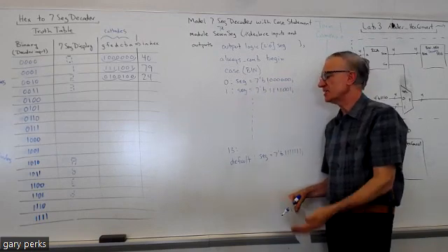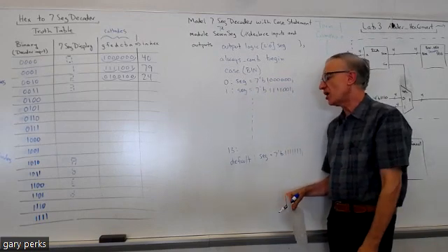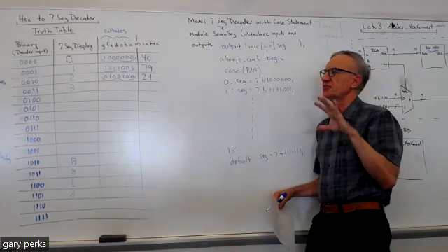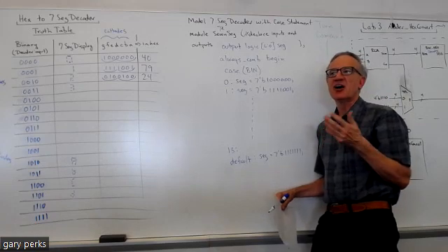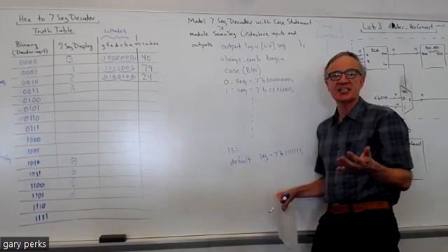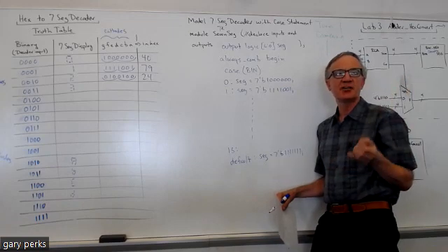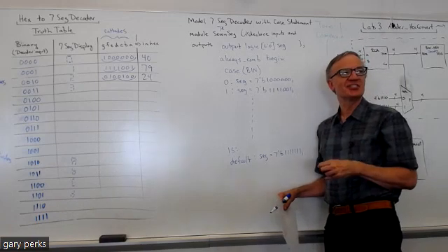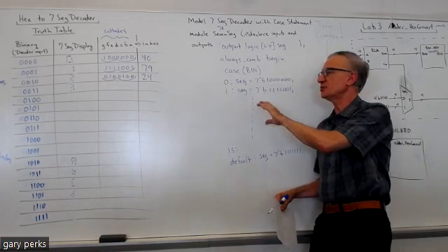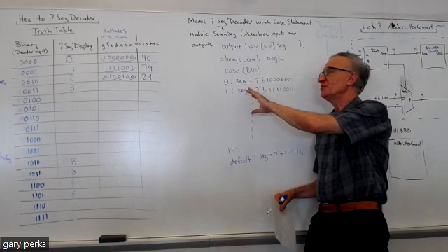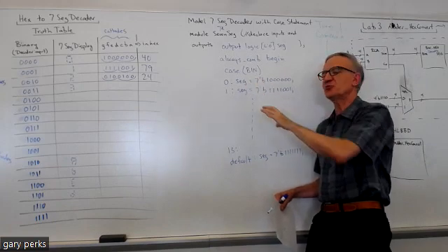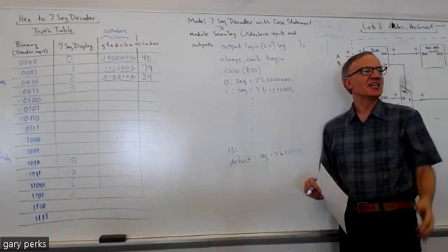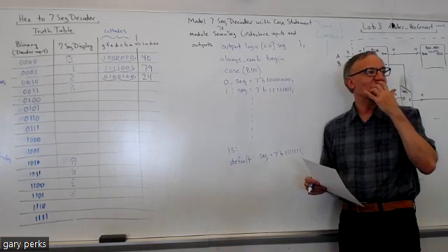I mean, an example in practice of why you would want a default is if you had some digital system that was in a harsh environment, like maybe it was on a satellite and the satellite got bombarded with solar flares or something. There's a bunch of photons that changed a bunch of bits all at once. Well, then you could get in a situation where you basically got hung up, like it was in between choices because several bits changed roughly at the same time, although nothing happens really at the same time, right?